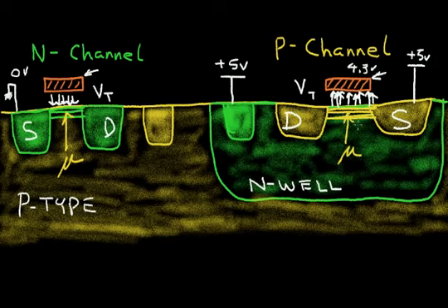So if you have a choice, you could either use an N channel transistor or a P channel. If either one would work fine, you generally want to choose the N channel since it conducts a little better, since the mobility of the electrons in the channel region is better than the mobility of the holes in the P channel transistor.